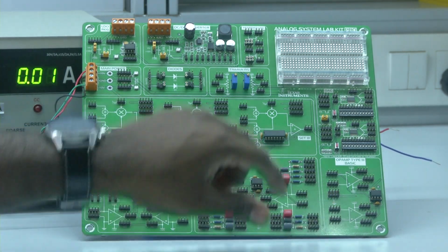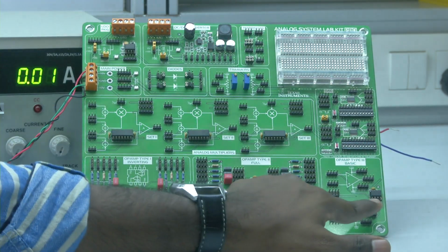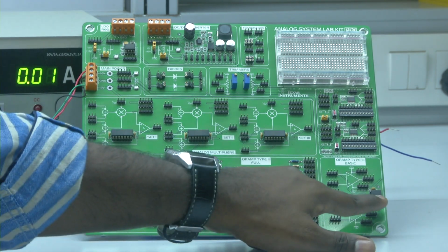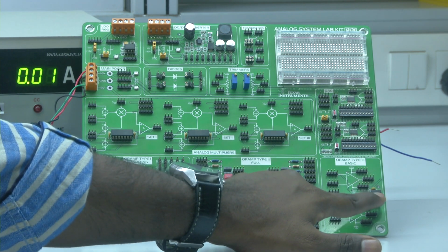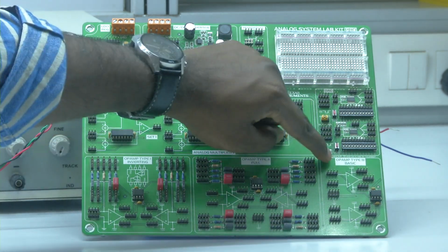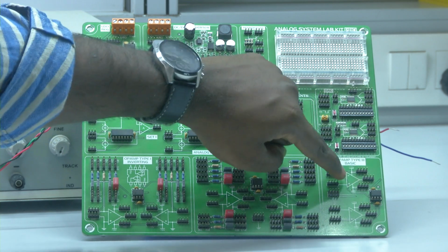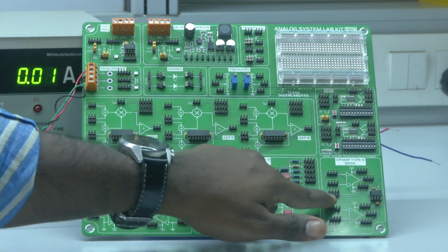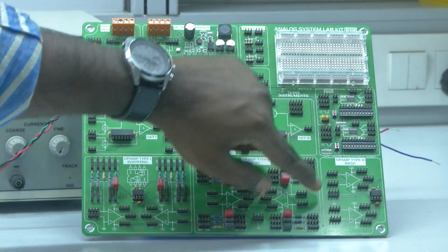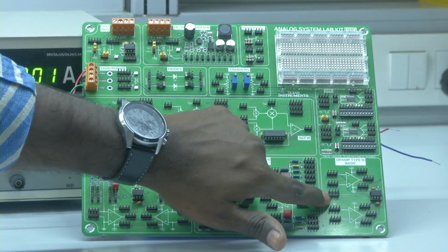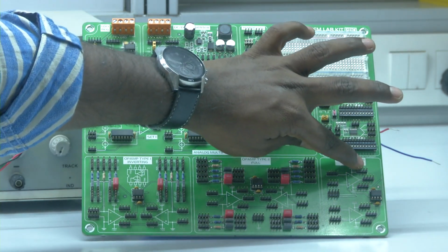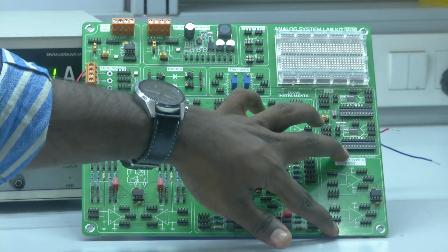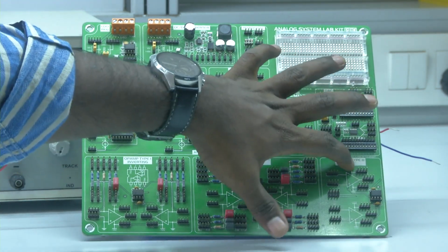If you carefully look, this is the IC, a TL072, which is a dual op-amp. Since it is very difficult to understand the configurations directly, the negative terminal has been connected with 4 banana connectors, the positive, non-inverting terminal has also been provided with 4 banana connectors, and there are separate pins for the ground and a 10 volt power supply. If we want to provide a single power supply to the board, we can do that for this particular subsystem.